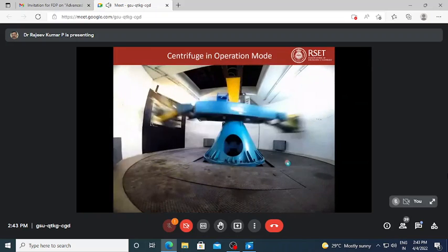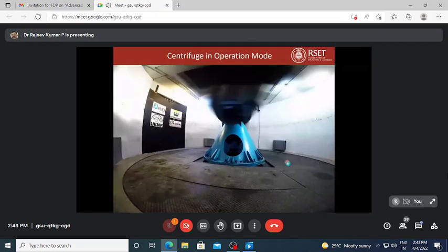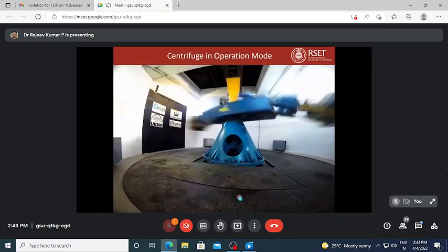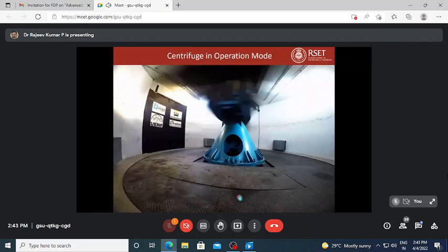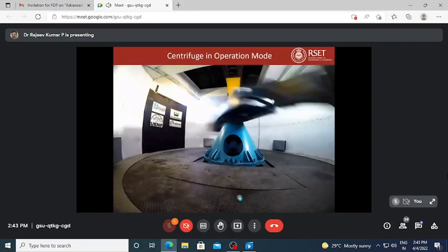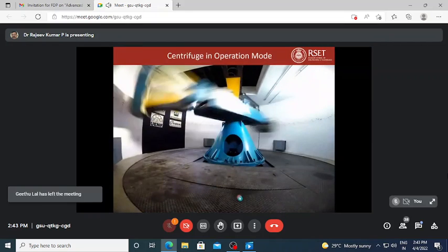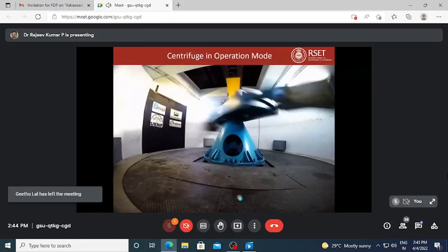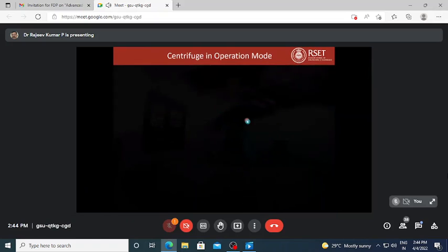Nowadays, very sophisticated instrumentation systems are used. Okay, you can even simulate rain in the geotechnical centrifuge. You see, it is simulated, and later on, when you switch off, it comes down to the stationary position. That way, you can check whether the centrifuge is working properly or not. The inspection window will give you a picture of what is happening online in the geotechnical centrifuge.